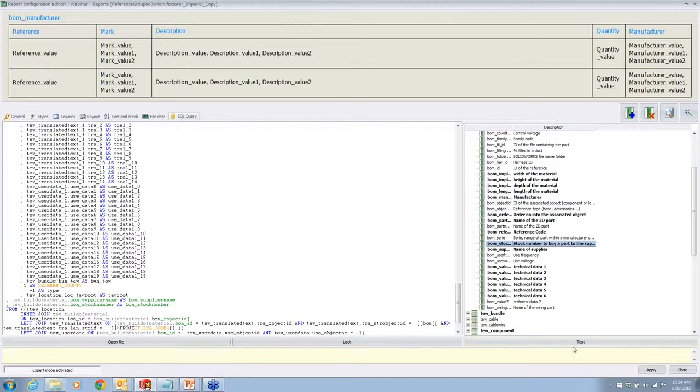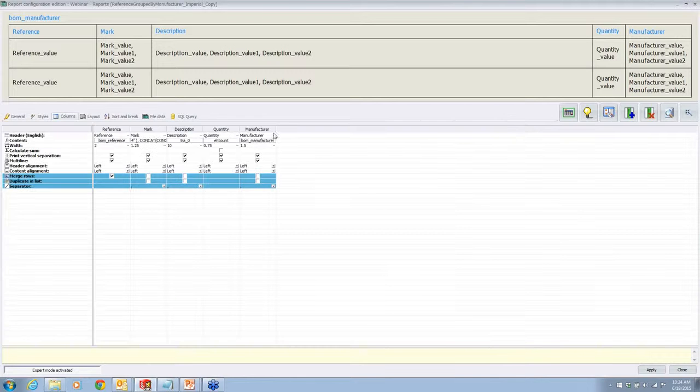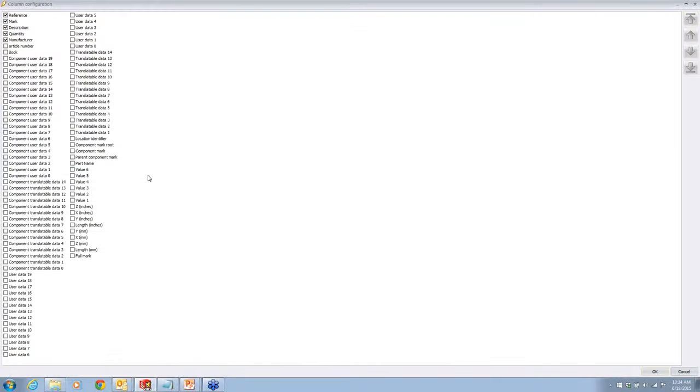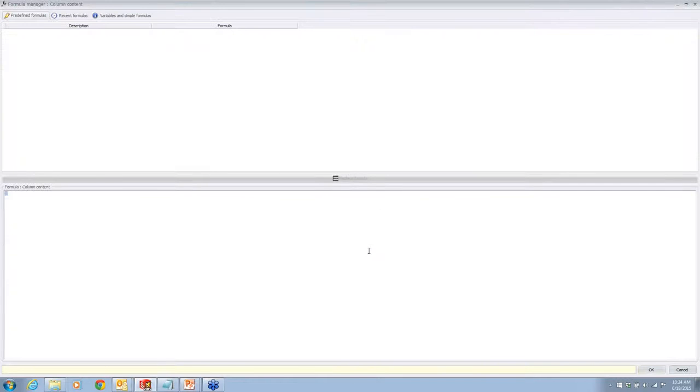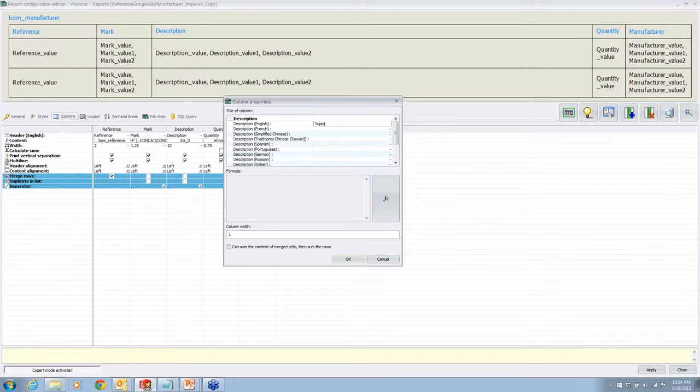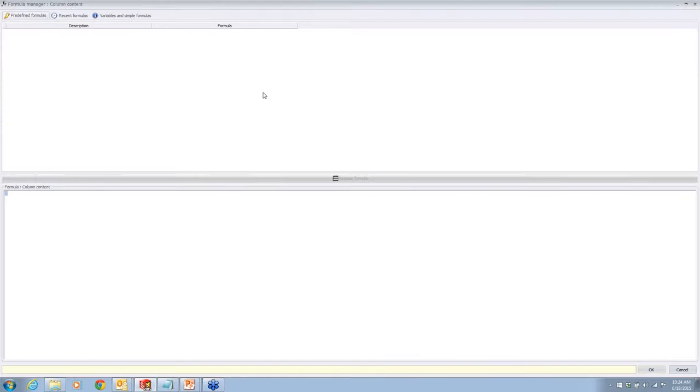So let's hit OK. Now that we've tested, we can lock this down. Let's come back out to our columns. But right-click. Still don't see that supplier here. That's because I never did that first step of adding the column to this window. So we have to come back and say, all right, now let's try adding this column to it. Let's give it a name of supplier, and see if I can find that variable this time.